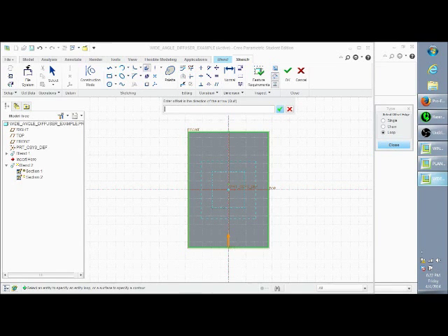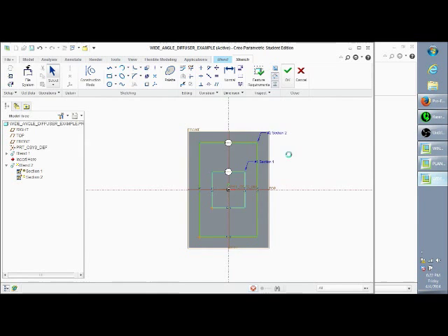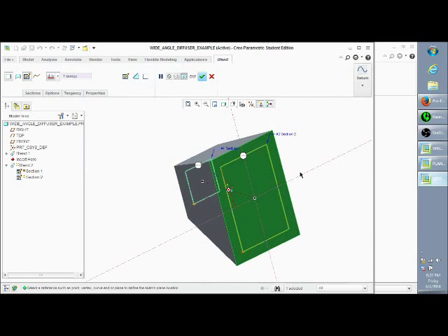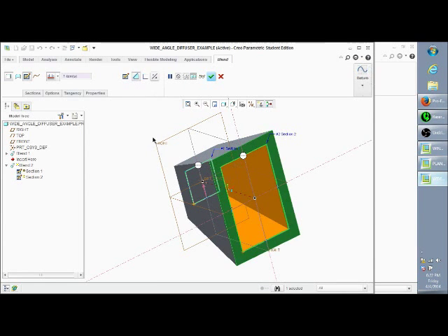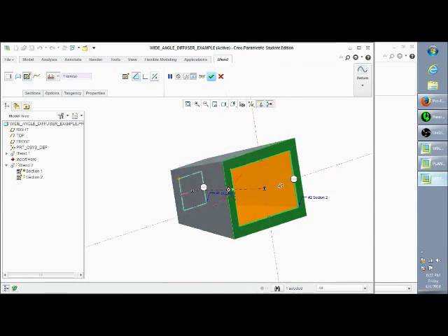And the arrow, pay attention to the arrow, because that's when you enter your direction up here, that's the direction it'll be going in. So you go ahead and enter in 0.75, because the thickness does not change. And you go ahead and click close, or you can hit middle click and that'll exit out of it too. And then you want to select OK, because we're done there. But notice that it's still not cutting away the material. So what we want to do is select this button right here, the remove material button, and there you go. It cuts away the material that we want.